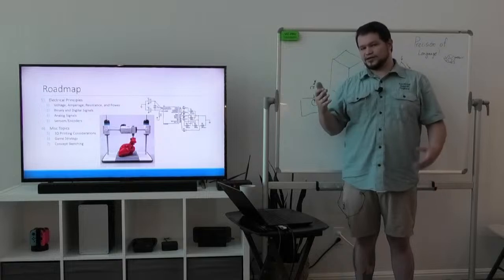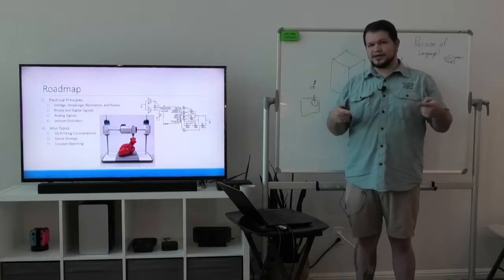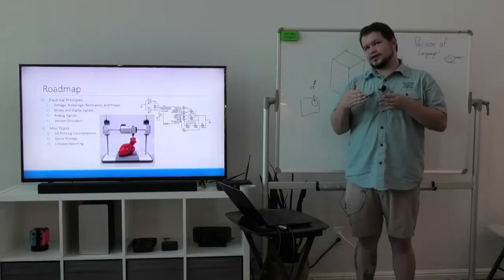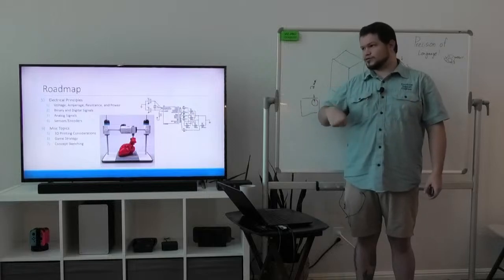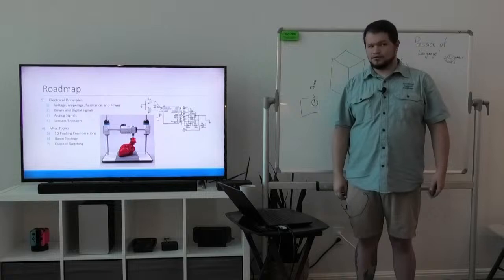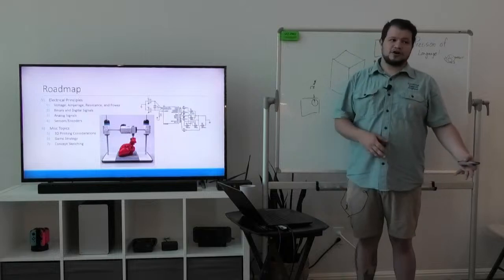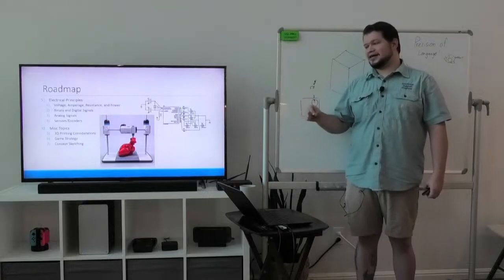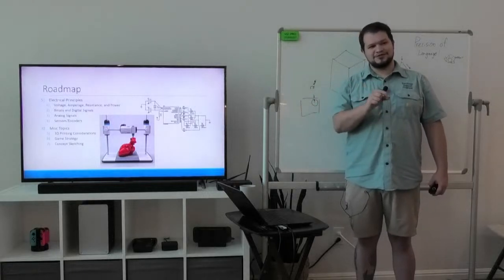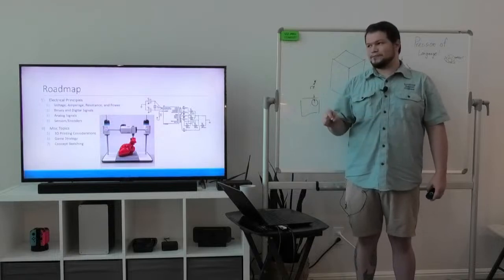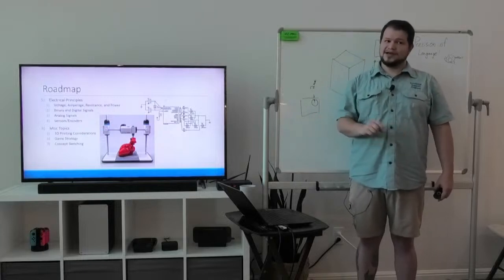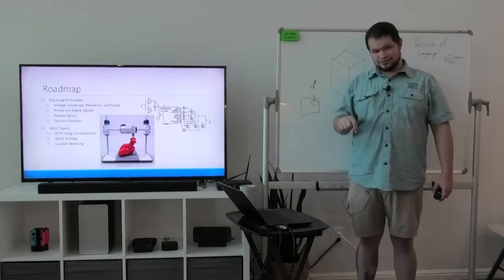If you are putting them in an actual CNC machine, they do make bits that are countersunk, or you get it laser cut and they make bits that are tapered for a countersink that you can put in a drill, and you can hand drill them yourself, with a drill press or even just a hand electric drill. You have to be careful you don't go too far because you're using your own level of precision, so be careful with that. Also be aware that metric bolts and standard bolts have different angles for flathead screws. Metric bolts are typically 100 degrees and standard bolts are typically 82 degrees. So when you buy your countersink, make sure it has the right angle.